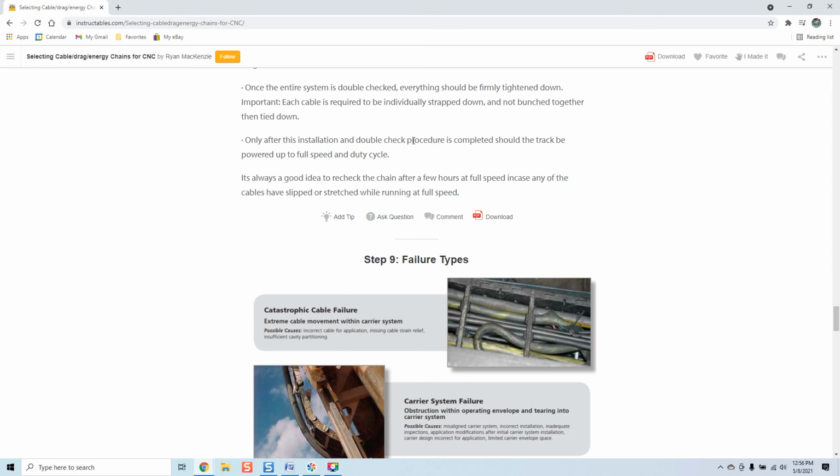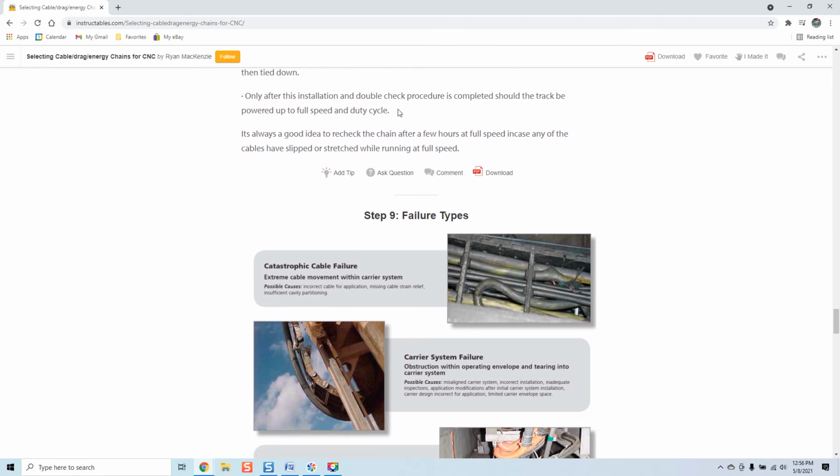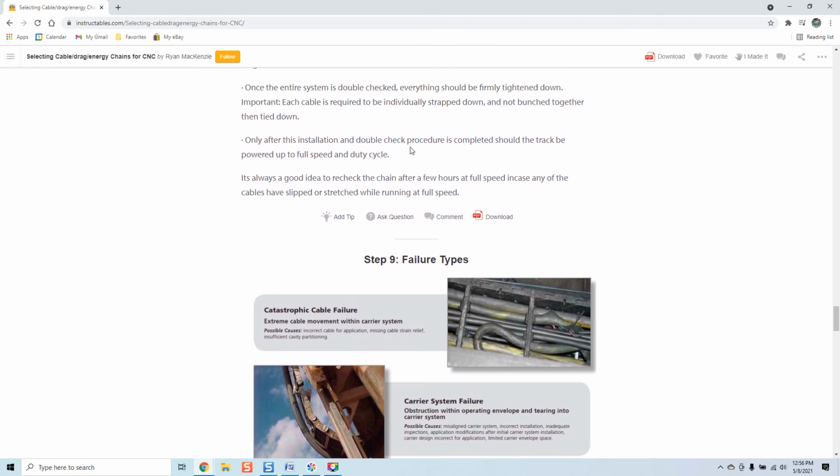And I recommend doing that over time, guys. If you're just setting your system up, get everything squared away. Make sure your coolant's on. Make sure your motor cables look good. Everything is good, there's no weird noises. And when I say weird noises, this is so interesting because I have guys that'll say, oh man, the axis sounds so great, everything sounds great. And then when they send me a demo video, like watch me run this project, I hear a stickiness in the background, or an odd noise that you just can't place.